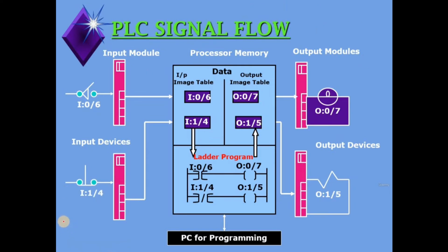Here you can see I:0/1, or it starts with 0 actually, means the 0 terminal. Accordingly 1, 2, right? And your last address will be I:0/15. Okay, and if you require a few more inputs, then accordingly you just need to change the word number, I:1.0. Okay, it's a very simple thing, right?